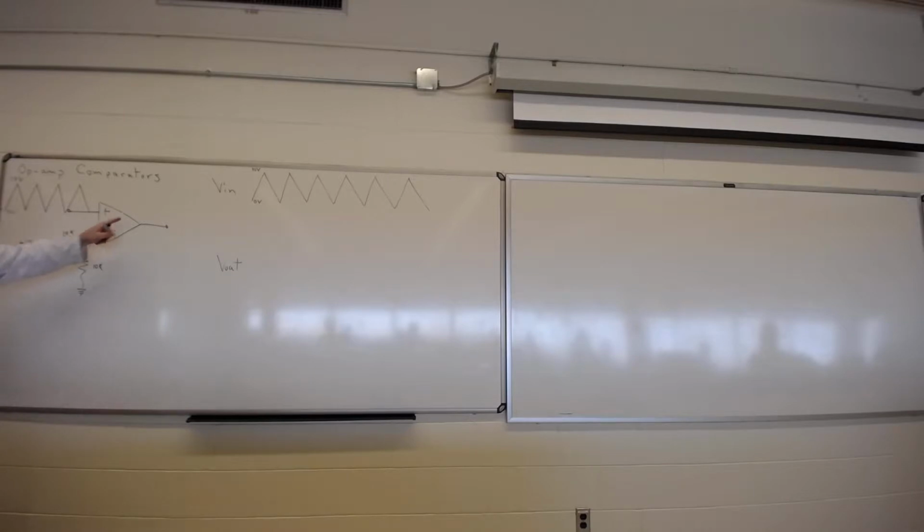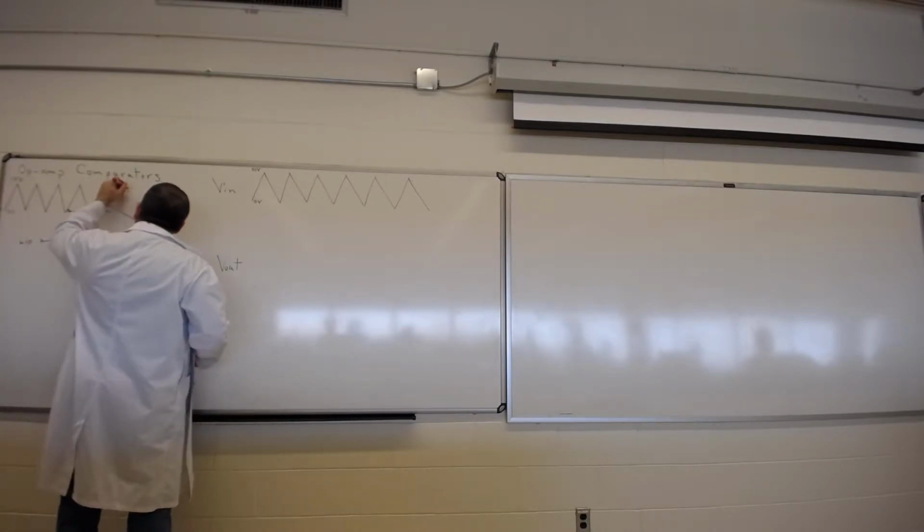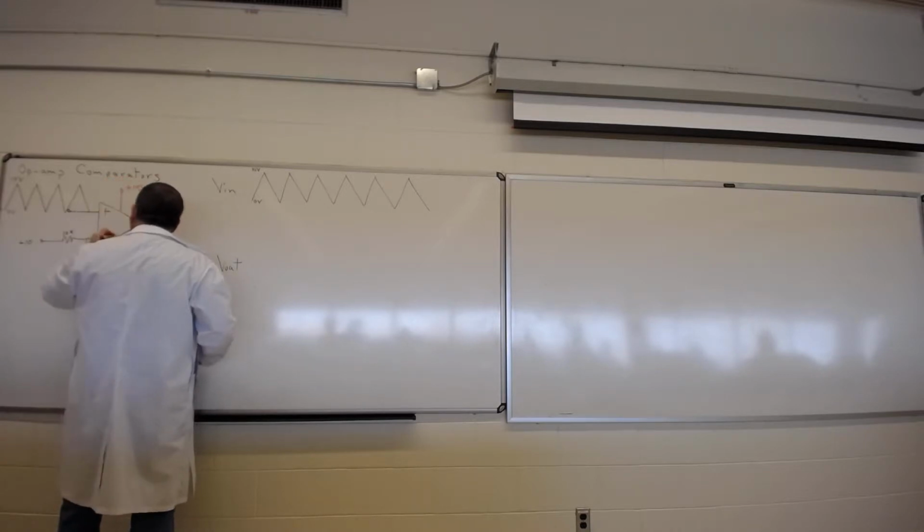So we'll start off by looking at this thing, and you'll notice in this case there is no negative feedback. This amplifier works basically using its open loop gain. So whatever's at the inputs, which is going to be a lot more than just a couple of microvolts, is going to be amplified at the output. So it's very important that I also indicate what the power supply would be to this thing. So I'm going to put, in this case, plus 15, negative 15.